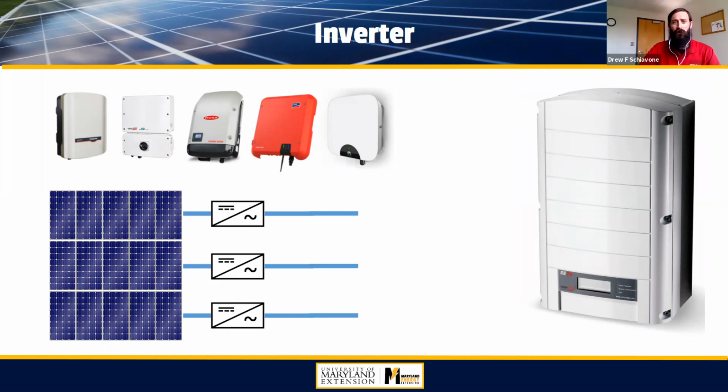With a string inverter, each string, or series of panels, is connected to an inverter, and then you can combine all those together. So in this example, you have 3 series strings together, and so an inverter on each of those, having a total of 3 inverters.